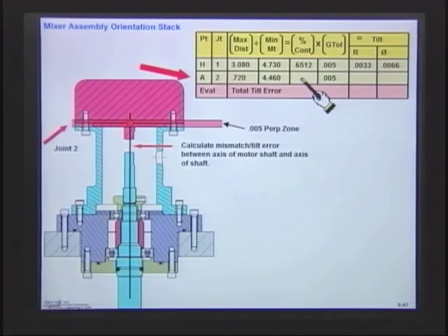Well, you see, we won't have much of a ratio here. You see how big the mount is and how short the shaft is? I think we talked about that when we originally toleranced the part, didn't we? So if we look at this here, let's figure out what our ratio is, multiply that out, and we get 0.161. And we'll take that ratio amount, that percentage, and multiply it times our geotol, multiply it out, and we find out that that gives us 8 ten-thousandths on a radius. It gives us 0.0016 on a diameter.